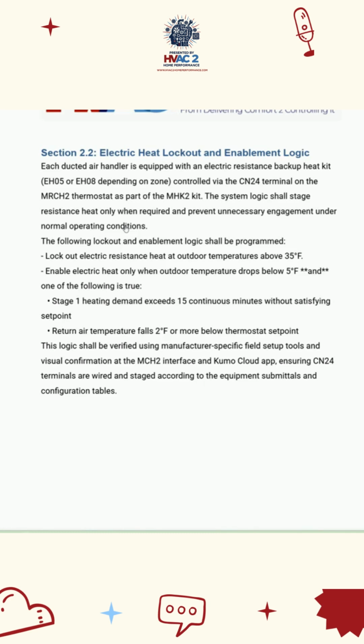Very cold climate, okay? So we know that what we have designed, if implemented the way that we design it, will service this load. We've done balance point calculations, heating degree day calculations, a bunch of different calculations that leave us assured that 98 to 99%, and I'm saying a literal percentage here, of the time, the system load, heating load, even in the negative temperatures, is going to be fully handled by the heat pump. So we spell that out in a little bit here.